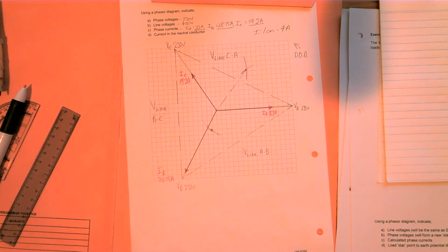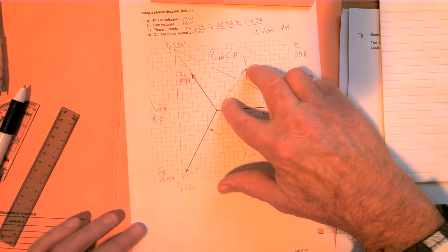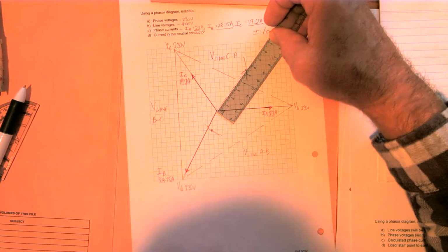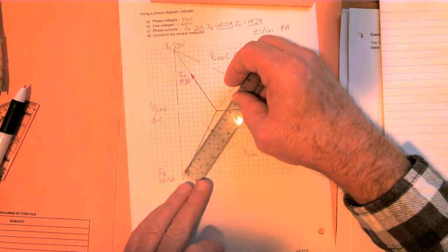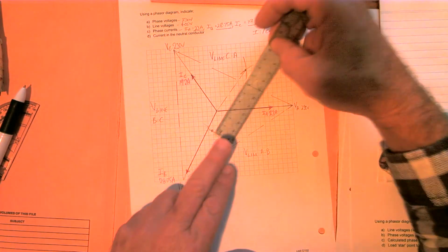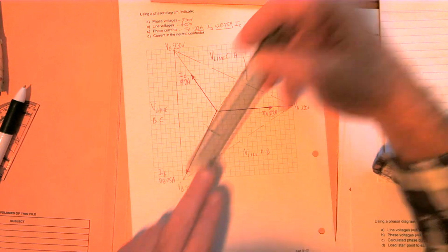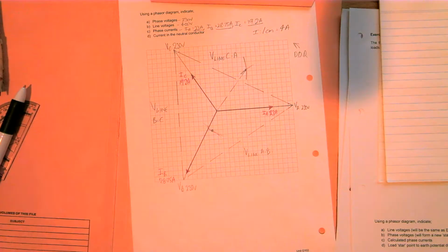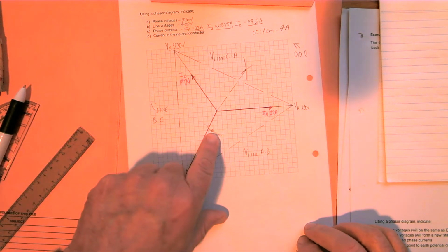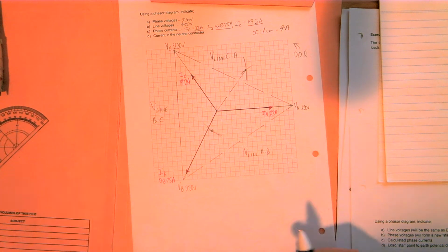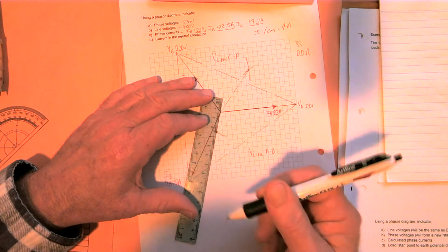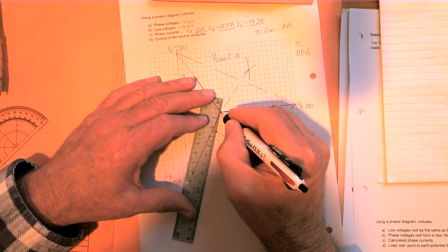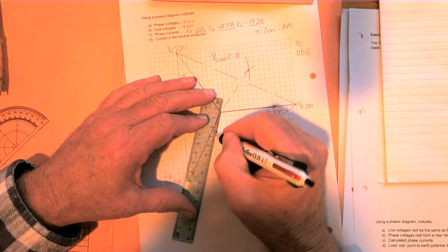We've got the same parallelogram, if you like, which has been done between there and there, there and there. So about nearly 5.5 and nearly 5.5. From there to there is about 7.5, and from there to there is about 7.5. So where those two arcs intersect becomes the resultant, or the value of your neutral current. So put that up there, down to that point.